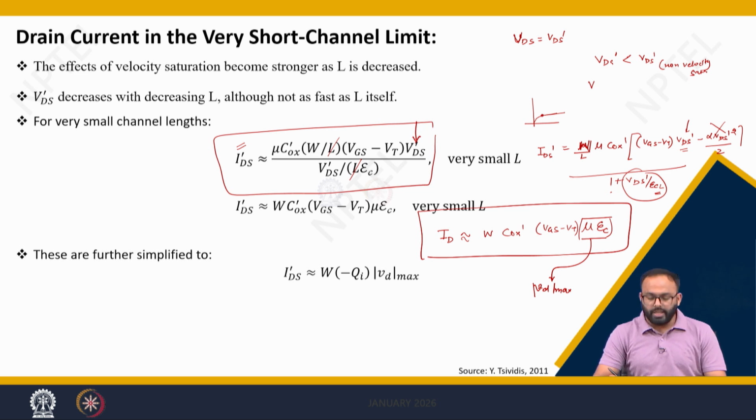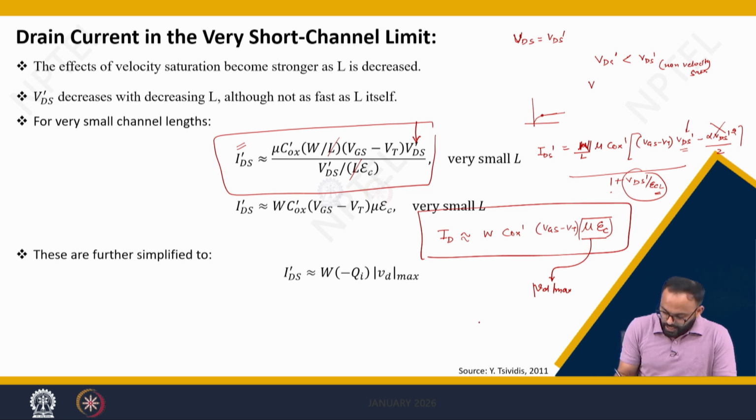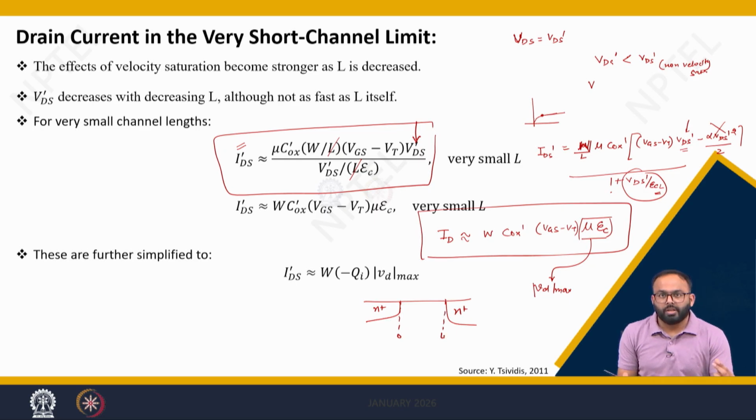This can also be justified as follows. If you talk about the channel where this is n plus, and this is n plus, and the channel starts from 0 and goes till L. The transit time of the carriers, meaning the time taken by the carrier to move from source to drain, is tau, which was given as L divided by Vd max. And we said that the carrier velocity is saturated, meaning this factor is constant.